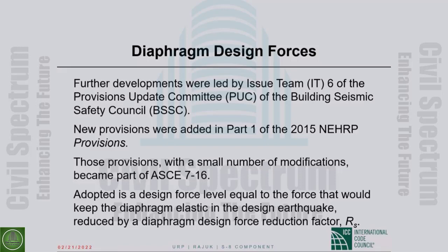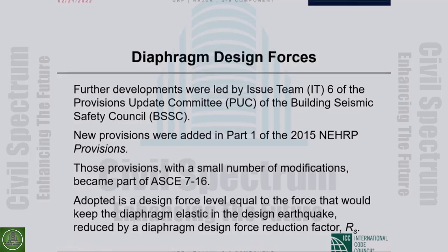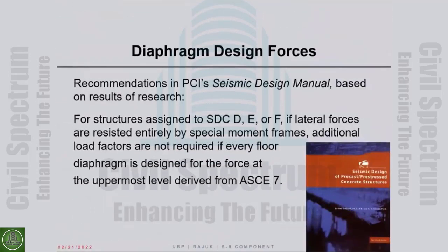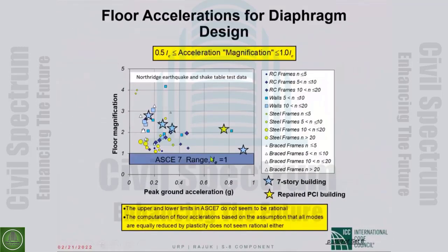This was a lot of work, and if you are interested, go to section 12.10.3 of ASCE 7-16. We have added a very extensive commentary to explain how things came about, and that is to reconcile this problem that observed force levels are high and our diaphragm design force levels are low.